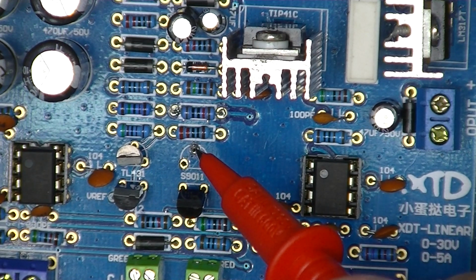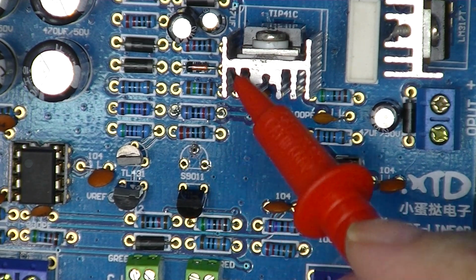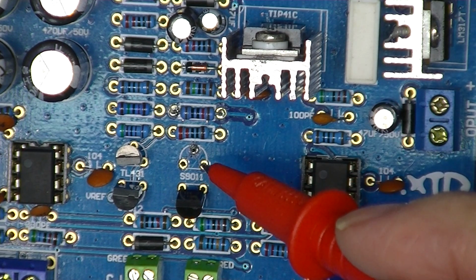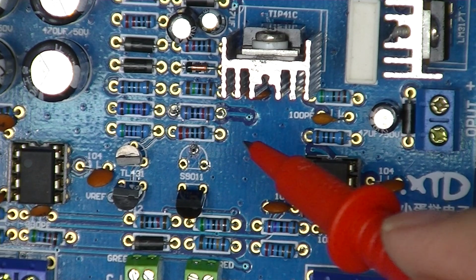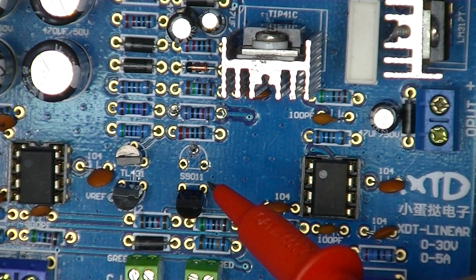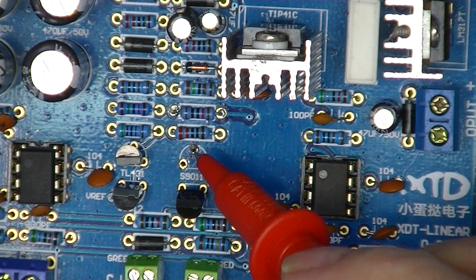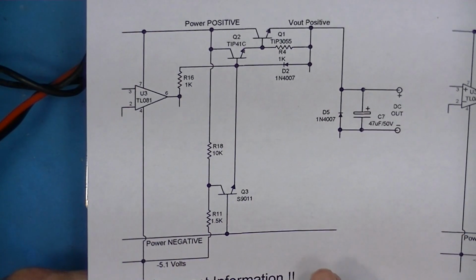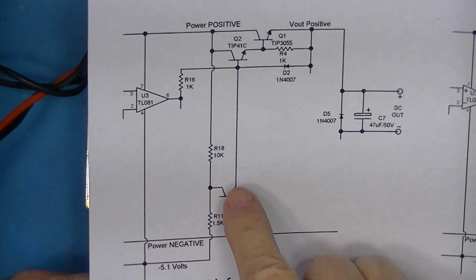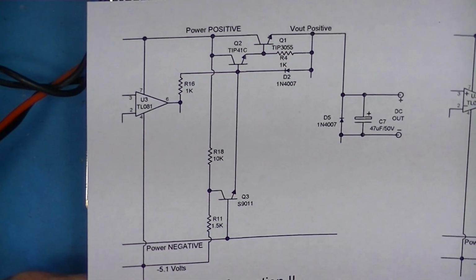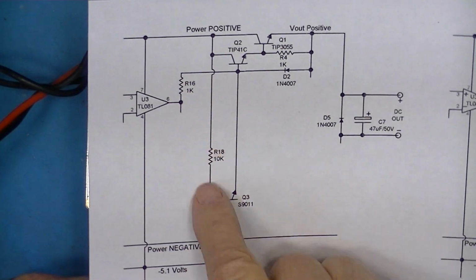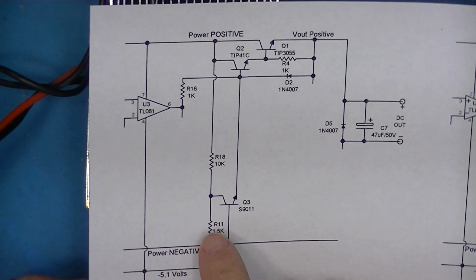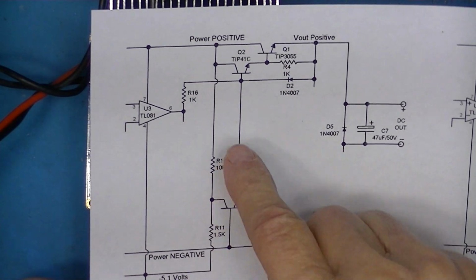Now, when I drew the schematic of this board, of course, it was not populated. So I used a magnifying glass and an ohmmeter to get point-to-point connections. Then I dropped into my schematic the components based on the silk screen. This is an abbreviated schematic of the events occurring around Q3. And this is what I came up with as a schematic. And I could not reconcile this. Like, in my mind, I don't know how it works.